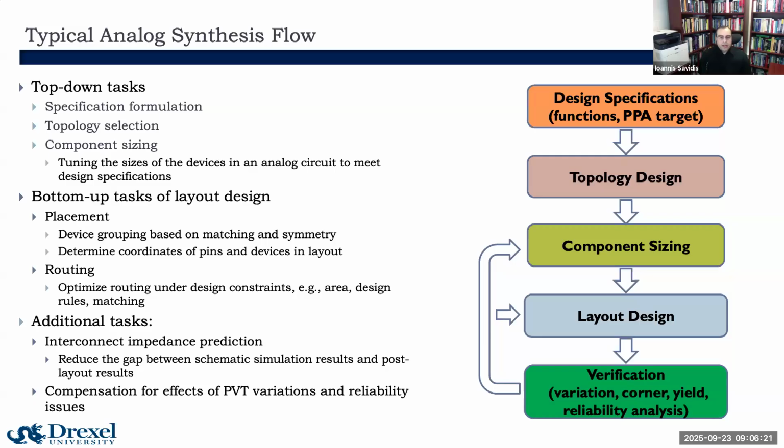There are additional tasks of interest in analog synthesis, one being that we want to have an accurate estimate of the impact of the interconnect on the performance of the circuit, as there's usually a significant gap between the schematic simulation and the post-layout simulated results. And the second task being the compensation for PVT variation, because temperature, voltage, and process variations often impact reliability, circuit specifications, and the robustness of the circuit.